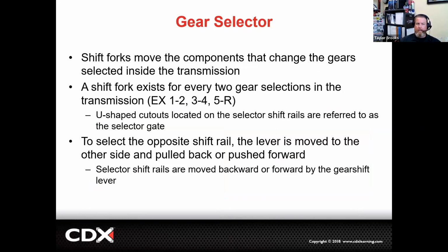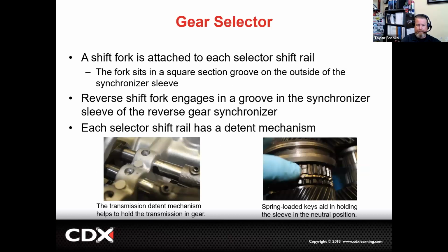The textbook, when we go into the next chapter, it goes into overhauling a transmission, and it's a T5 transmission, which is a very typical 5-speed design transmission with 3 underdrive ratios, 1 direct drive, and 1 overdriven ratio. And the synchro layout is going to be the same for a lot of transmissions. The S40 transmissions we're rebuilding in class, those are also 5-speed transmissions, and they go off of the same shift strategy for the gear selection.